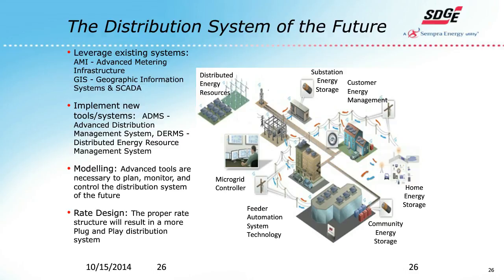Modeling, really looking at a whole suite of advanced tools, and not only to monitor and control the distribution system, but you think of this in the context of how does the integrated T&D system look? Because as the aggregation of units rolls up, if you start to get reverse power flow out of the distribution substations, then you start pushing power out into the transmission system and the impacts associated with doing that. And how does that all get modeled? How does all the information get exchanged?